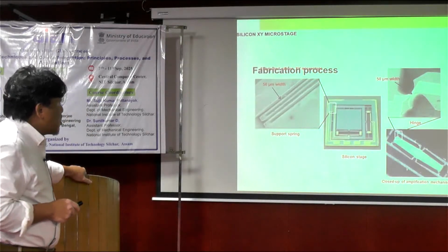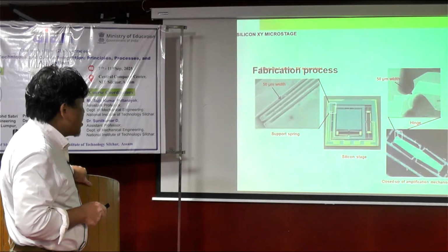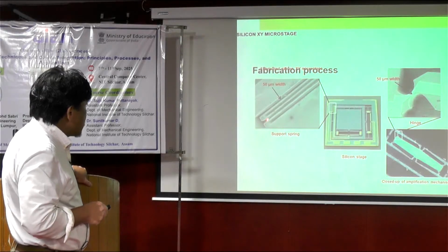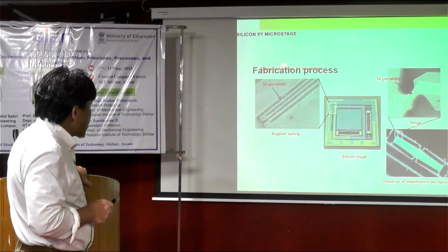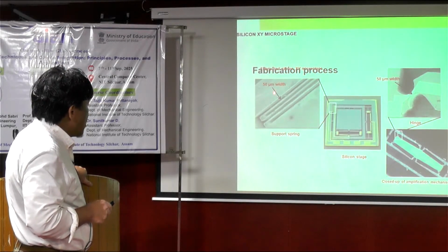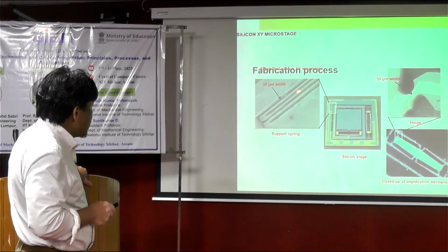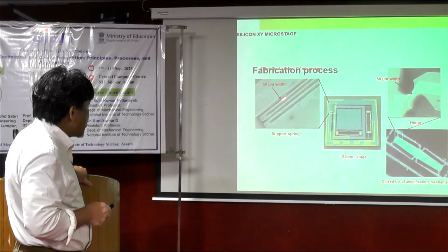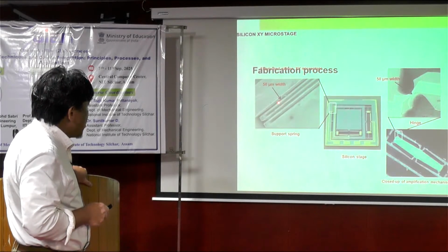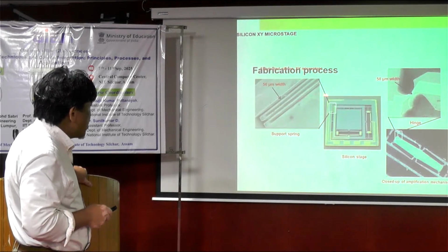Next is the detail of the fabrication, what we obtain. As I mentioned before, it's quite difficult to obtain good structural geometry when you do the process. However, this is relatively good, with a 50 micrometer width of the support spring, the serpentine spring.